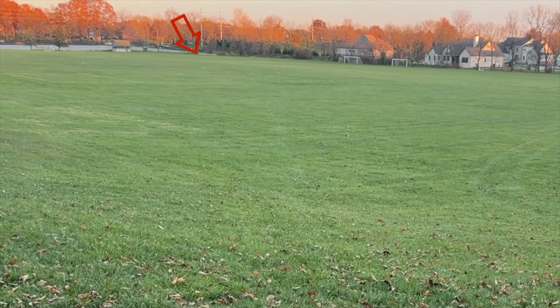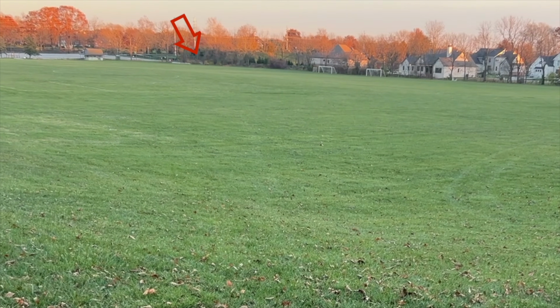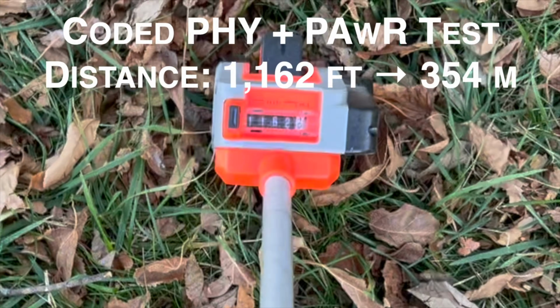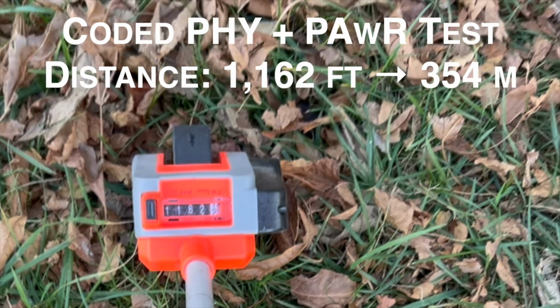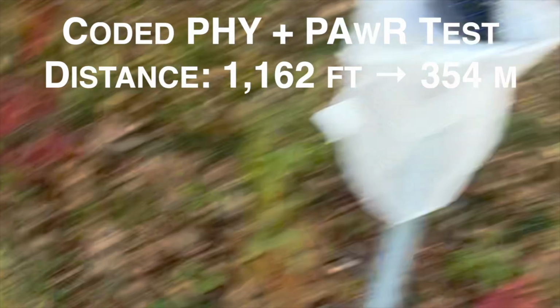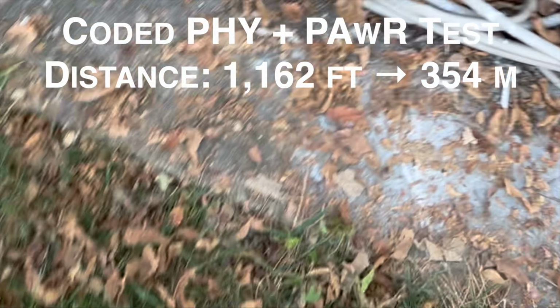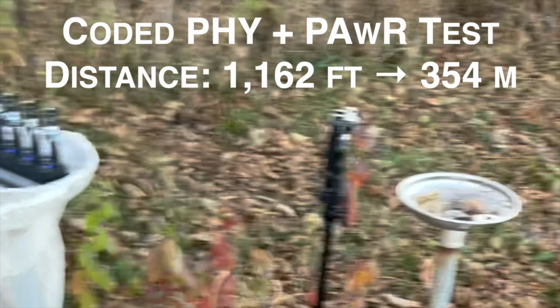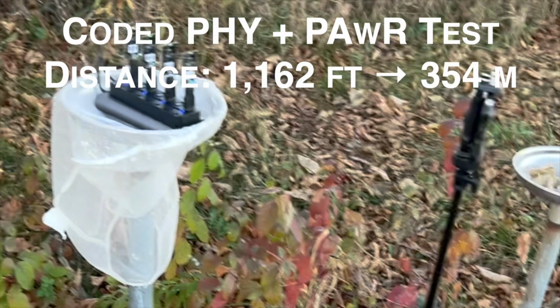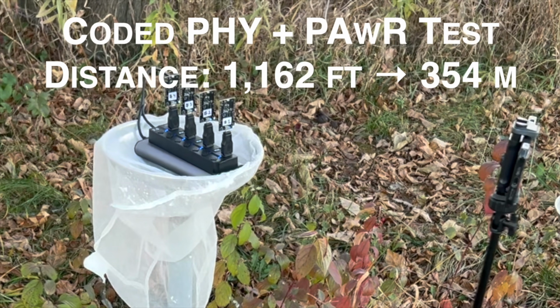So now I'm just going to measure the distance from here all the way back. This is the test with Coded PHY and periodic advertising with responses. All right, so distance is around 1162 feet, or 362 meters, and I'm back at the home base. So that's around 360 meters or so. So pretty good distance. We couldn't get farther than that on the field, but this is how far we can get. We were able to cover a good distance with Coded PHY.